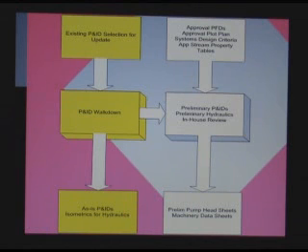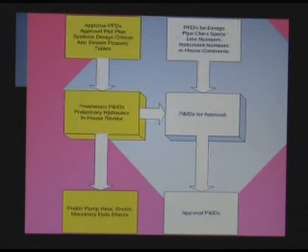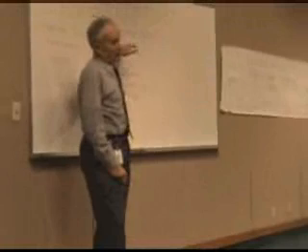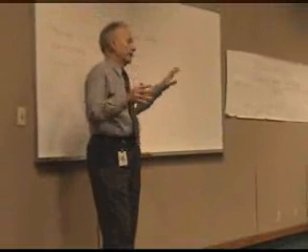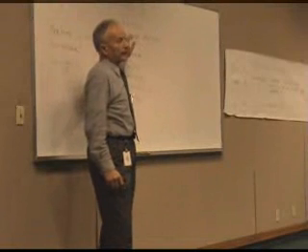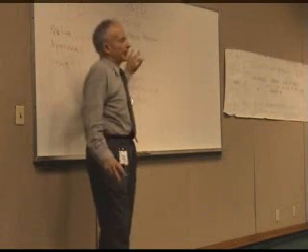And the preliminary issue of the P&IDs is produced and reviewed in-house. I put this in parentheses, in-house review, because sometimes we don't even do that. Sometimes we do more of these. If the definition is not that firm, we can have more than one preliminary in-house review P&ID.